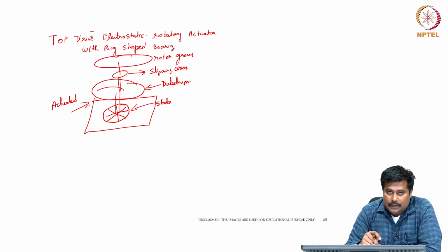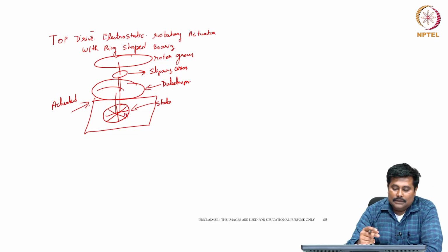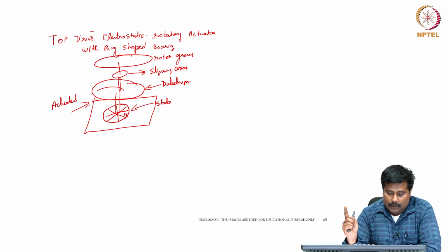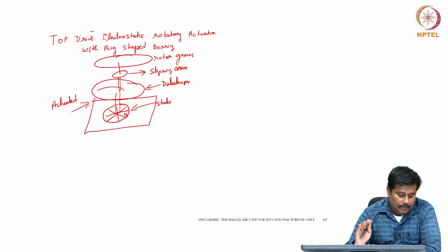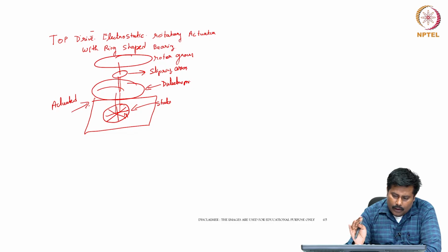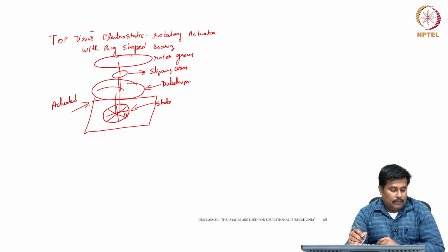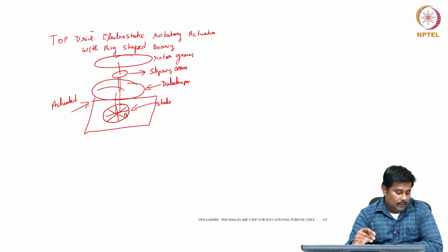Each and every slot is energized in such a way that this will result in the rotation of the dielectric material, and the slip rings which are available will be used for appropriate control over the rotation, and then there will be a rotary ground which will be available. So in the earlier cases we have seen linear actuators. These electrostatic actuators are now configured also in the form of a rotary actuator.